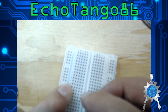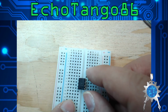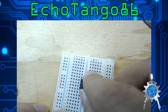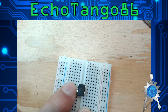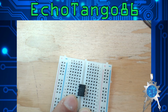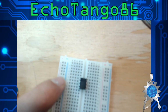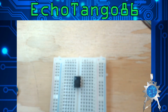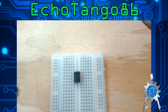Now you want to be able to have a nice line that goes from where power and ground are to the top and bottom of your chip. So this would be okay because you have a nice line from where the power goes into the chip or the ground into there. But if you had it, let's say, up a couple more, now you can see that there's, I'm not quite sure why they did that on the breadboard, a gap here between where the power and ground is, so it would have to have this awkward angle, and it makes it kind of hard to figure out what's going on when you're running wires. It gets kind of ugly pretty quick.